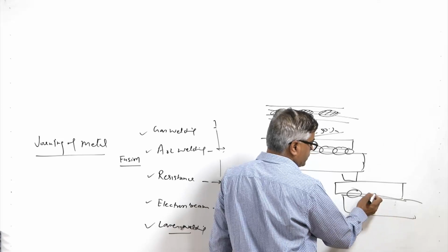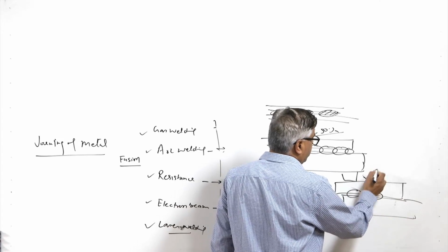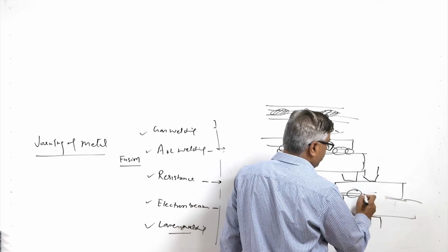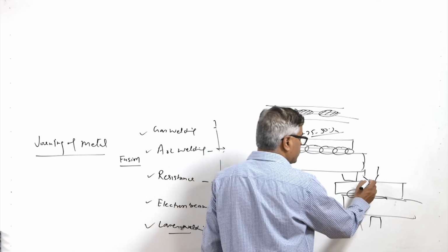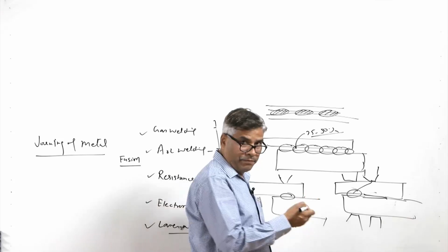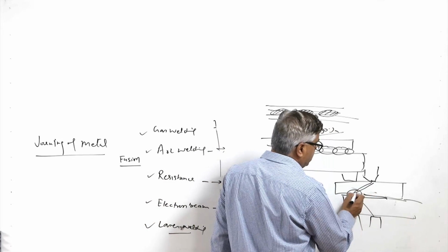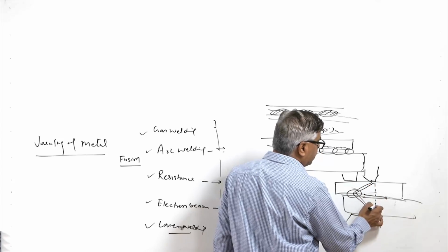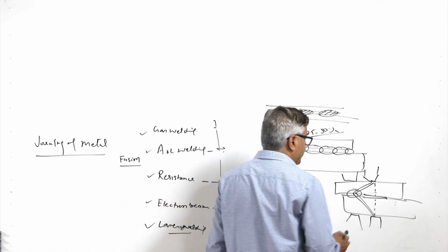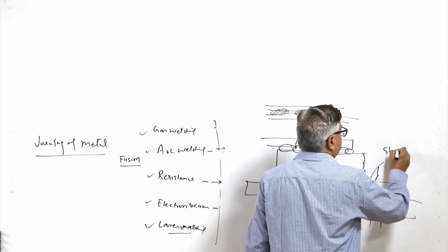Thereafter, if another spot is to be made, then shunting of the current will occur. Although the electrode positions are here, at this location there is no metallurgical continuity initially. So, the flow of current will take place through the already developed nugget to complete the circuit. This leads to reduced current flow through the location where the nugget is actually to be made. This kind of effect is called a shunting effect,